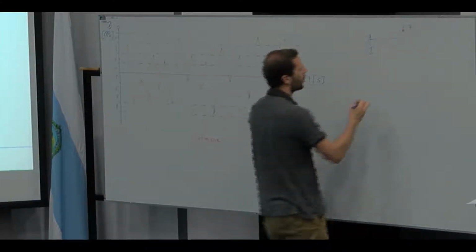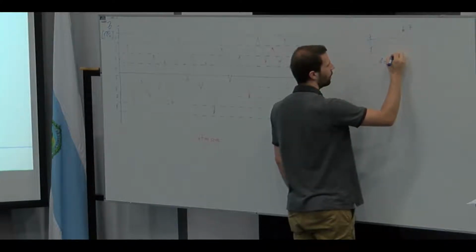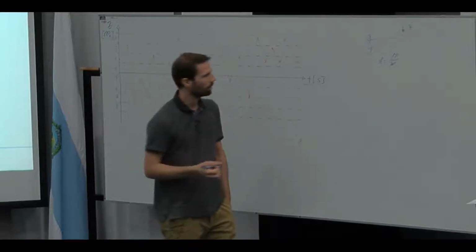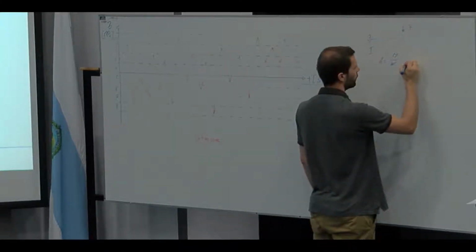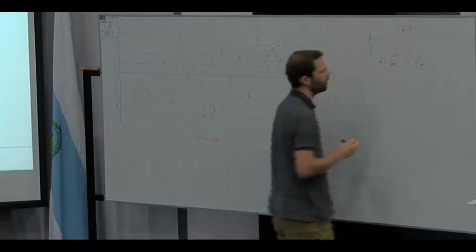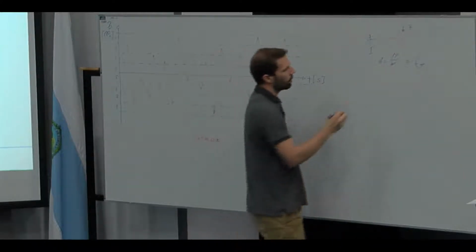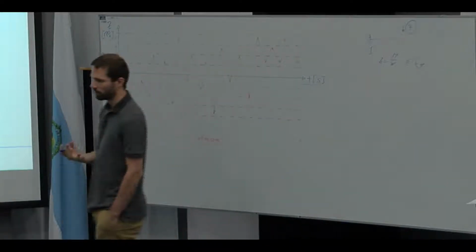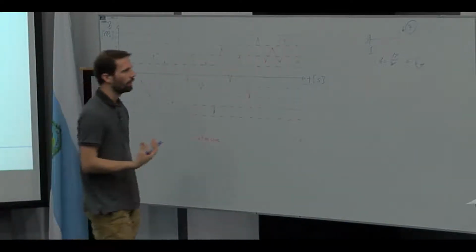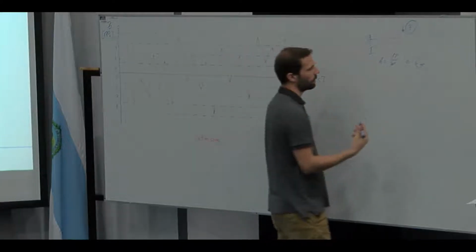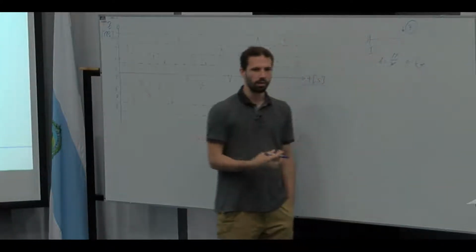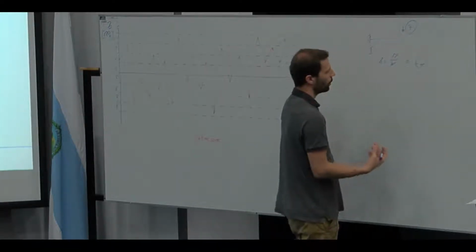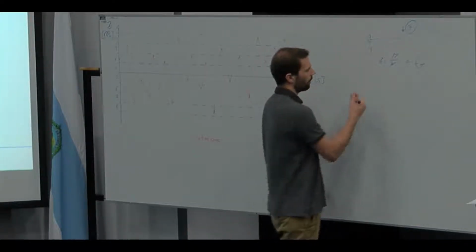At the end we do our analysis by sigma equals M over W, and this has to be smaller than fy. At this point our force is always a maximum value, to take care of the highest impact, and also of some impact which we maybe have not thought about.